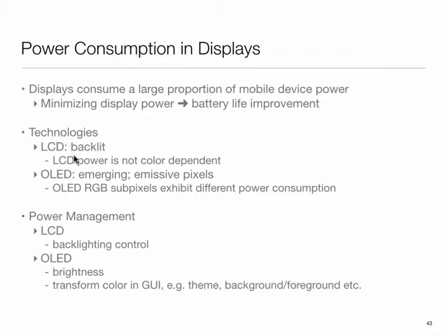These two displays work in a very different fashion. LCD displays are what are called backlit displays. There's a light behind the display, and when you turn on or off a pixel, the LCD either blocks the light or lets the light go through. So it is in itself not generating any light. The light is being provided by a backlight, and that is what you are seeing.